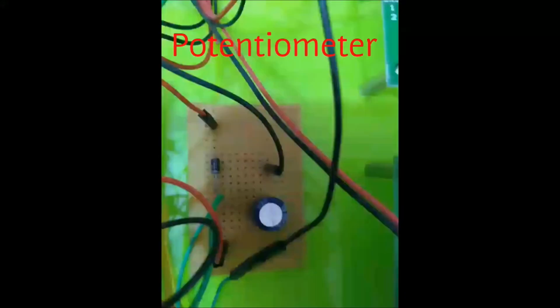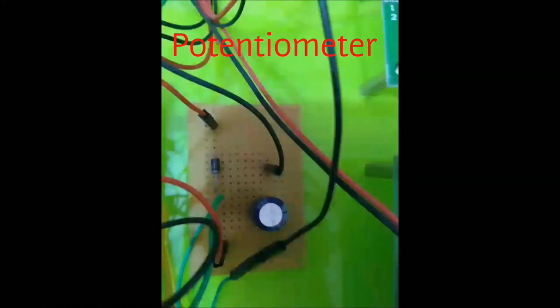A potentiometer is connected with the water level sensor to bring the input voltage to the microcontroller to 3.3 volts. An optocoupler bypasses the 12 volts output from metal proximity sensor to 3.3 volts.